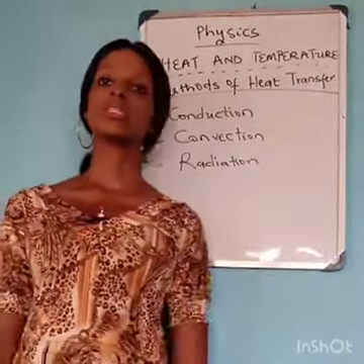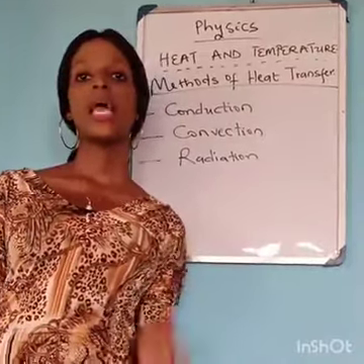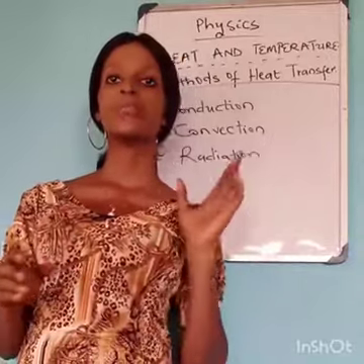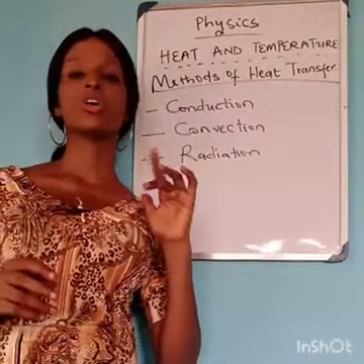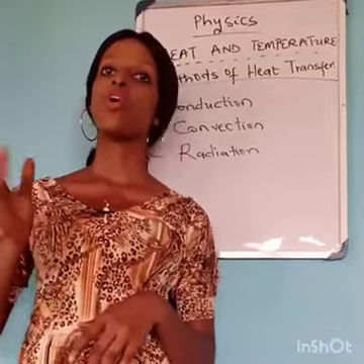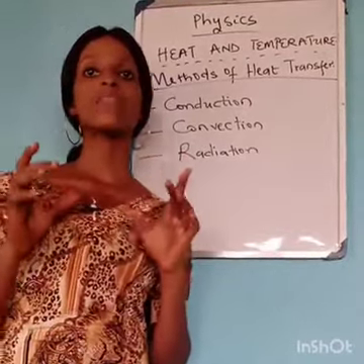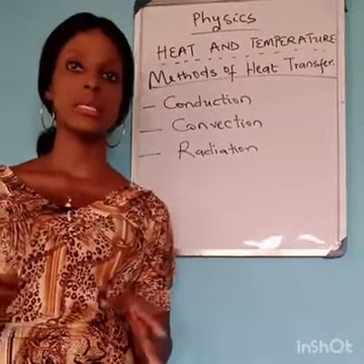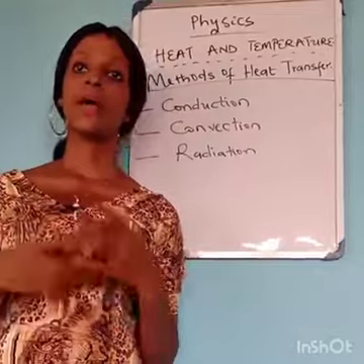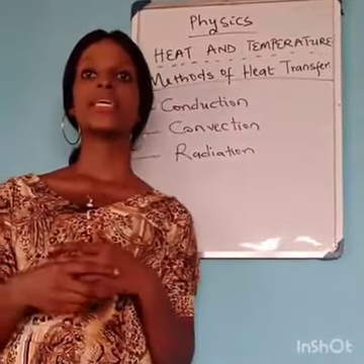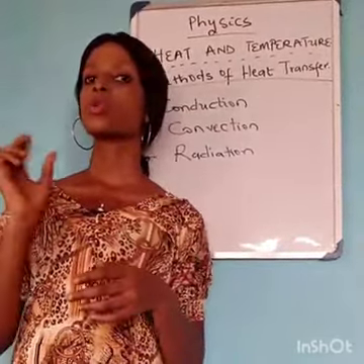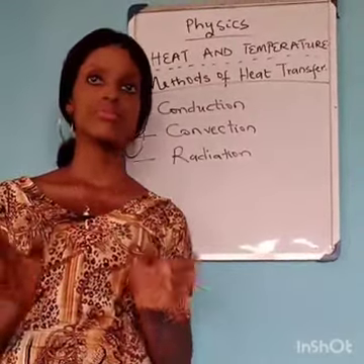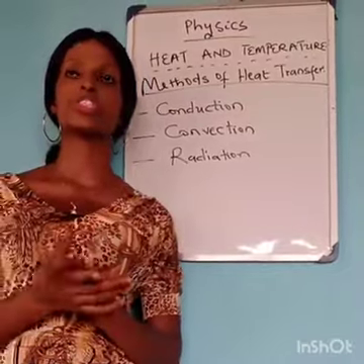Treating conduction first. Conduction is simply a method of heat transfer in solids, whereby heat energy is transferred from a region of higher temperature to a region of lower temperature, while the average position of the particles of the material remains the same. In conduction, a material or a medium is needed, yet the molecules or the particles contained in this material do not need to move to transfer the heat. They actually vibrate around the mean position.